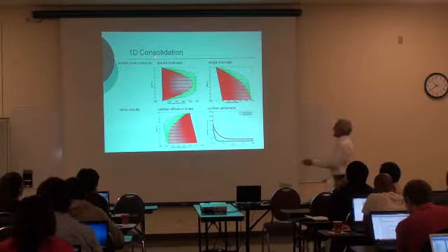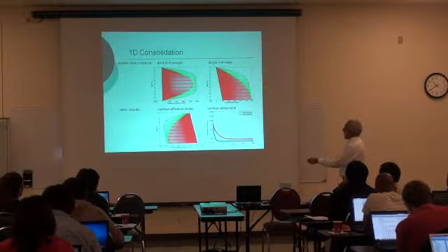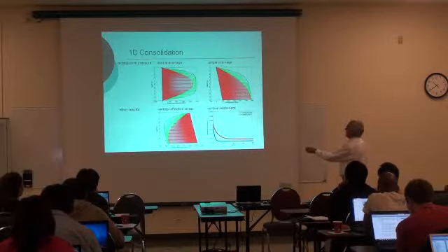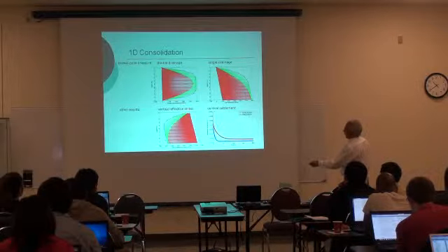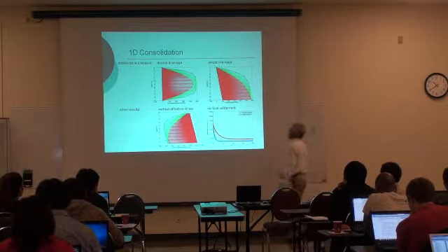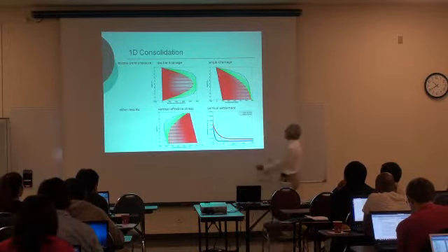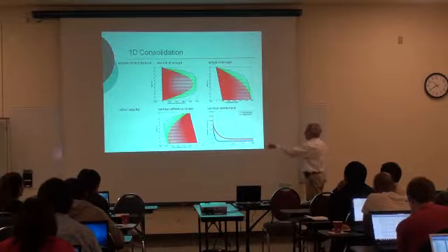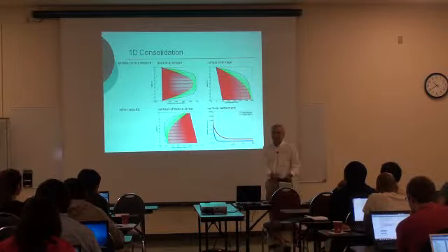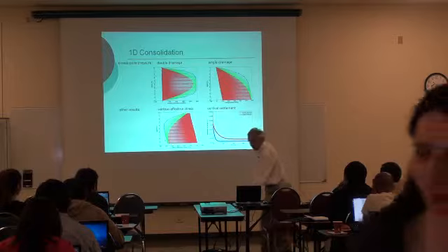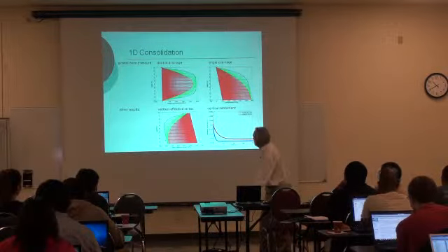This is just results that show pore water pressures with time for a doubly drained situation. If it is single drainage, you see that the pore water pressures dissipate only at the surface and not at the bottom. And you see the evolution of the effective stresses. You start with very low effective stresses, and then you reach a final situation. And of course, you see how the settlements develop. If you have a double drain, the settlements happen much faster than if you have a single drain situation. And that's that typical thing that you want to do in geotechnical practice. That's why I developed this little thing to show that it's possible to do.